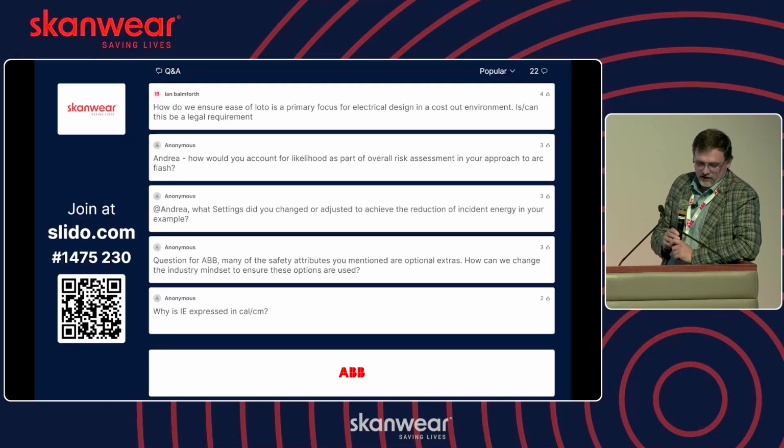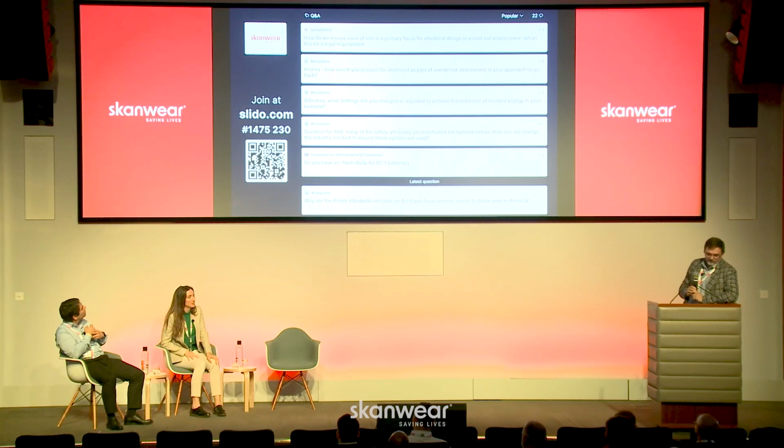There's a lot of questions for you, Andrea. What settings did you change or adjust to achieve the reduction of incident energy in your example? Mostly the changes were within the instantaneous region of operation. That will typically give you the instant gratification, so to speak. We changed the low voltage circuit breaker, and we changed the medium voltage relay settings as well. I don't know the exact numbers off the top of my head, but basically we tried to make the protection more sensitive, so it tripped faster and at a lower set point than it did originally.